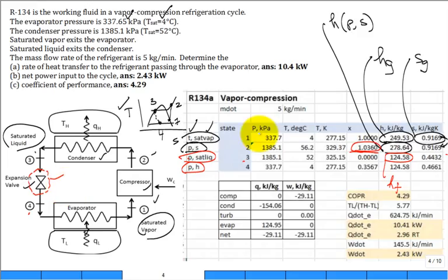Right. Once we have our table of properties, what column is the most important? The enthalpy column. Then you go to our table of heat and work transfers, and we have a standard assumption about the compressor. Now, if anybody's been around a real air conditioning compressor that's been running for a long time, and you reach up and touch it on the side, guess what? It's hot. The compressor is really, really hot. Now, in practice, do the engineers wrap an insulating blanket around the compressor? No, because if there is a little heat transfer, it's only going to help. So if there's a little bit of heat transfer to the outside air.